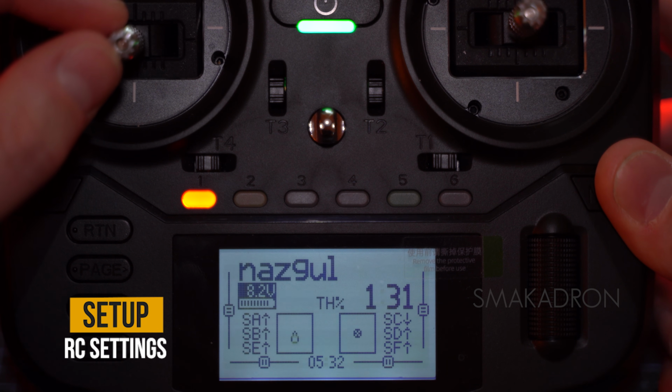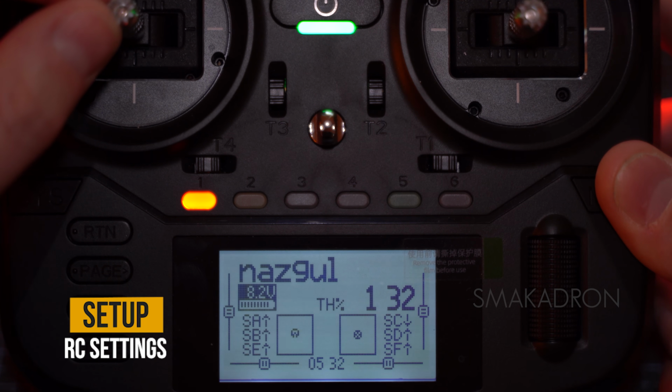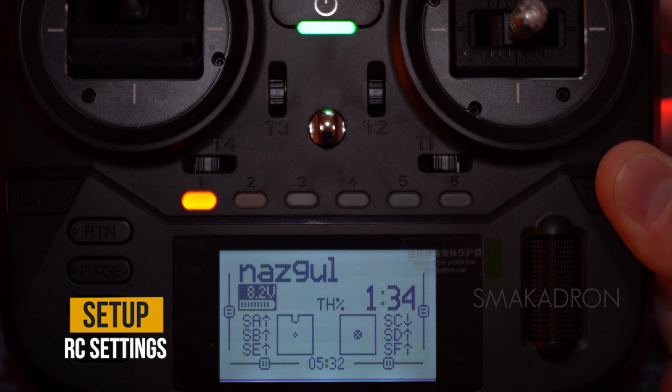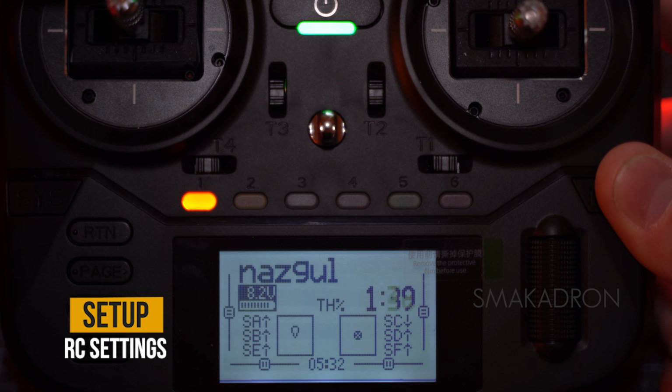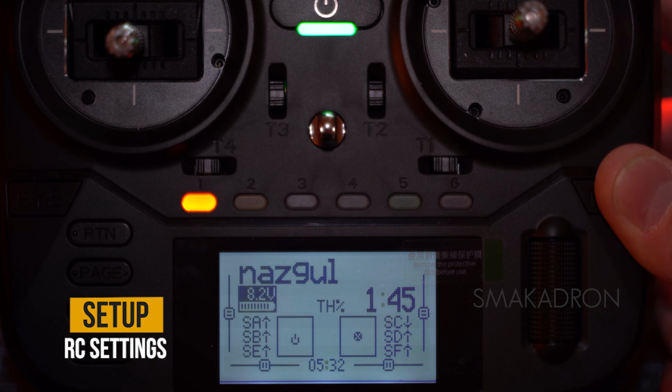It is calculated in real time at the maximum value and at 50% of the maximum value of this source. For example, when the throttle stick is at maximum, the timer counts in real time, but if the throttle stick is at 50%, the timer's counting speed slows down by 50% relative to real time. This is useful for those who want to know how much time the drone was really being pushed hard.